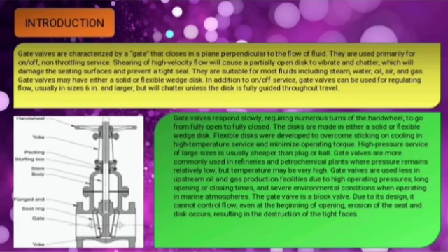The discs are made in either a solid or flexible wedge disc. Flexible discs were developed to overcome sticking on cooling in high temperature service and minimize operating torque. High pressure service of large size is usually cheaper than plug or ball.